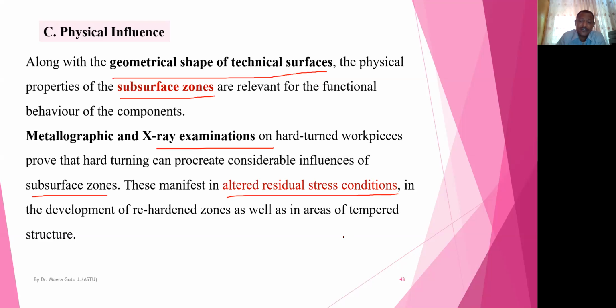The machined surface can have different strengths, hardness, wear resistance, and corrosion resistance due to the presence of residual stress in the surface or subsurface. So this can be reduced either by right implementation of optimized cutting parameters used in machining hard materials, or by a heat treatment process after machining.